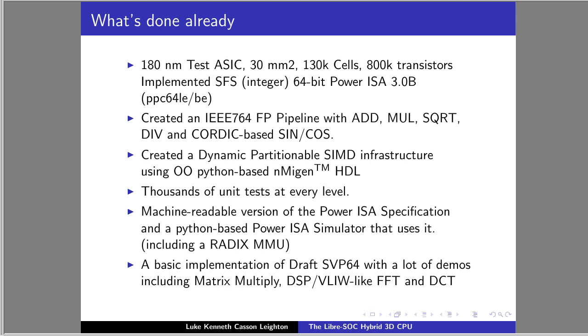Then we could run those unit tests side by side with the HDL, single step the core, single step the simulator, extract the register file, compare them, extract the memory, compare that, and if there is an error, report it. So in this way, we went literally from the specification to a simulator based on the specification to HDL, which was accurate to the spec.